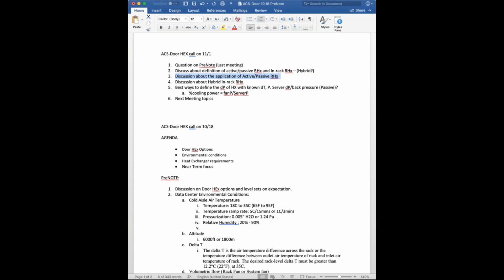Sorry, do you mind elaborating on more compact heat exchanger designs? When I mentioned compaction, I was talking about, let's say if you eliminate the fans from the IT, and you're removing the air-cooled heatsink and replacing it with a liquid-cooled heatsink, there could be some IT designs, let's say 4U or 2U IT designs, where you can go down to less U space. So in essence, higher density per rack per server.